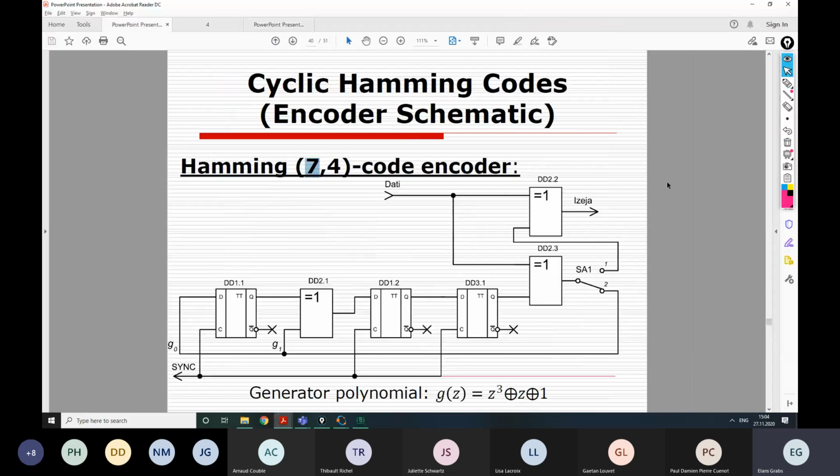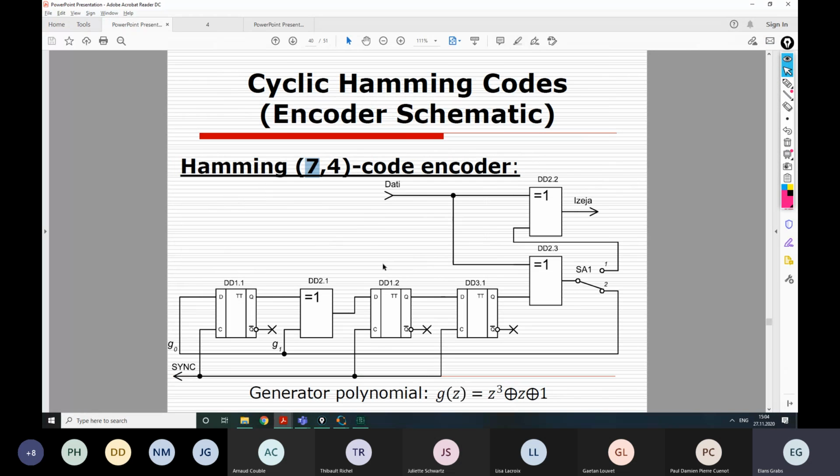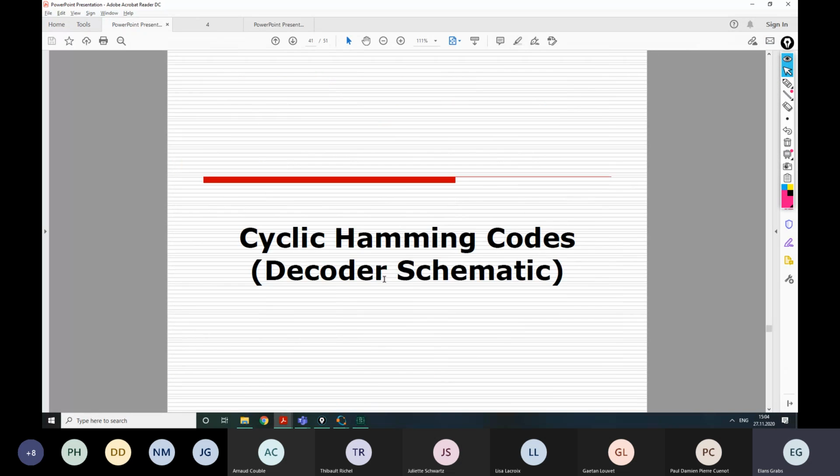Whereas for this schematic, you would need extra 2 flip-flops and up to maximally 2 more XOR elements. And that's all. That would be for M equal to 31. Much more compact. Also much more convoluted operation logic. In this case, it was quite simple, we had equations and we just drew the schematic according to those equations, then in this case the logic is much more convoluted and difficult.